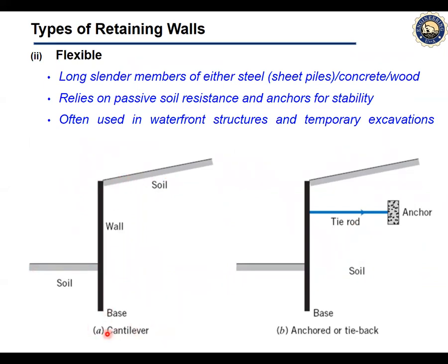In figure A, we set it as a cantilever wall. If this is the slope that wants to be retained, the upslope, and it's a road like the way we saw in the previous figure on the sample practical situations, we can put a cantilever retaining wall. For a much higher upslope load, to take the higher amount of extra loads of the soil, there is a modification.